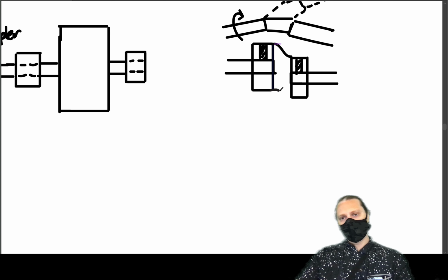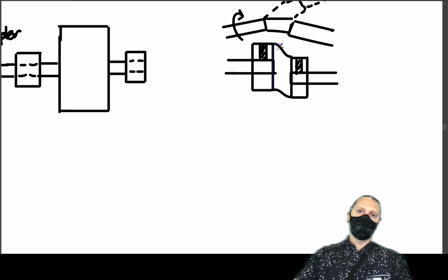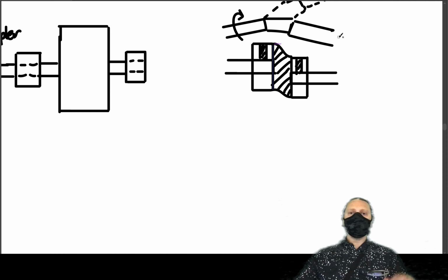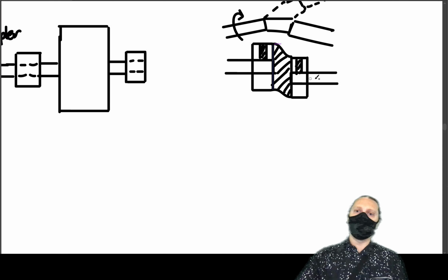This will flex in between by essentially bending along these cuts. And the torque here gets transmitted here without trying to displace it too much.